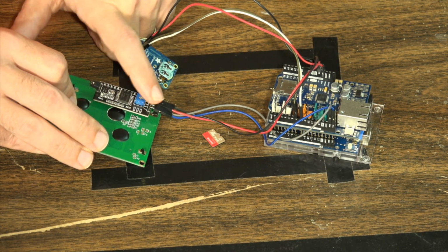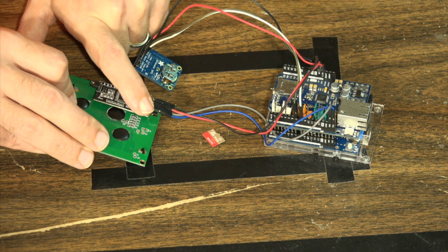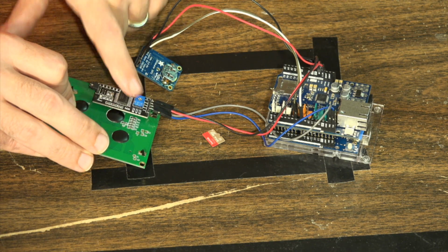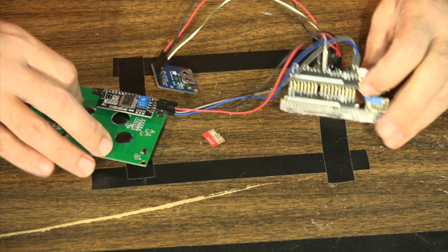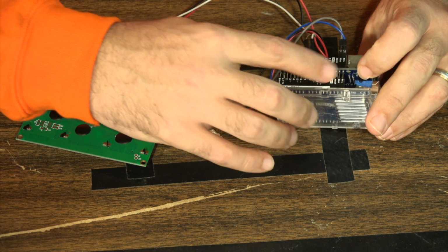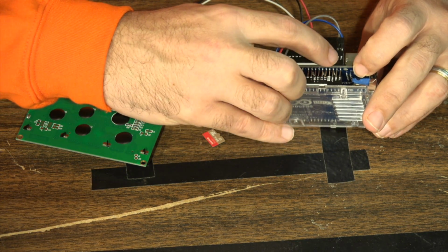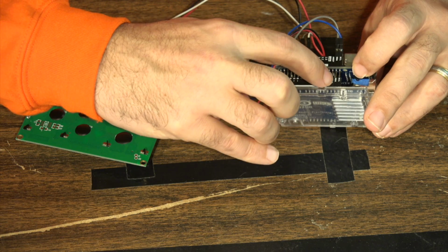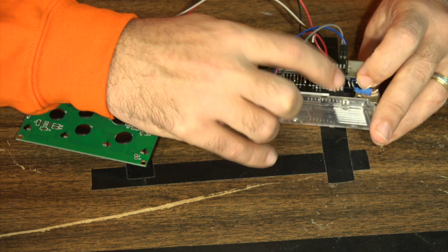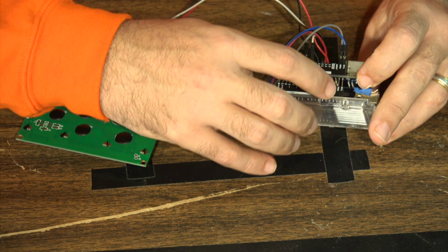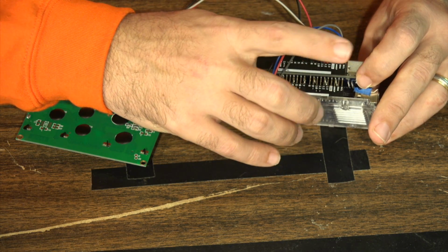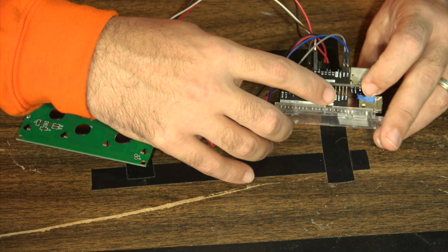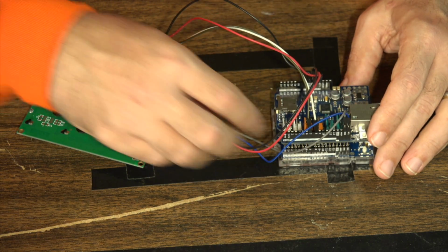So the I2C screen is using the 5 volt. It's connected to the ground. It's connected to the SDA, and it's connected to the SCL over here at the top. Again, using a standards-based shield like this, the SCL and the SDA pins will go all the way through. Something to be thinking about is if you're using a different shield, not all shields have the SDA and SCL pins go all the way through. So again, be careful about that. That's one of the quirks you can run into.